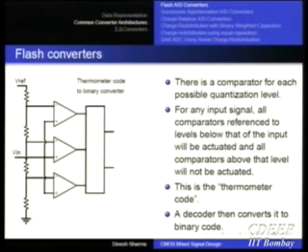I'll also ask you to think what will happen if I had to make the corresponding version of D to A using this trick. But this one is an A to D converter. What I have is a reference voltage here, and I divide it equally into equal steps. So this will provide those thresholds, and remember that the half bit offset will be accounted for by a value of R, which is not identical to the rest.